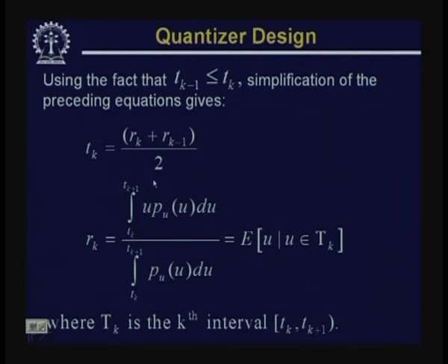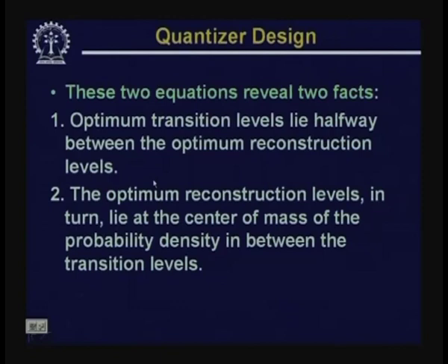So, this optimum quantizer, or the Lloyd-Max quantizer, gives you the optimum reconstruction values and the optimum transition levels in terms of the probability density of the input signal.